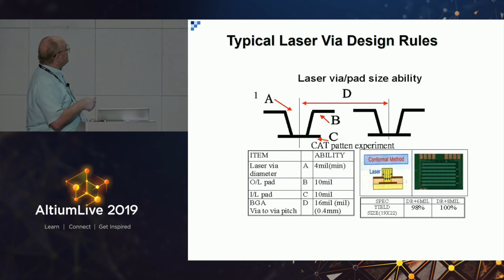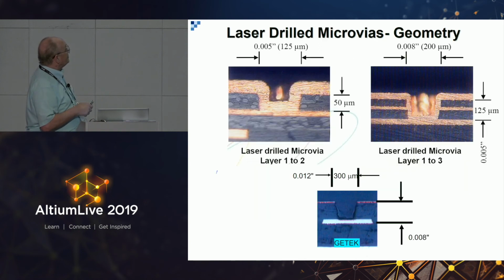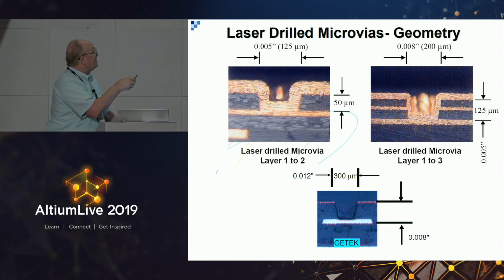And so, we don't need to talk about typical microvias. These are our typical microvias. This is what we call a skip via because it goes down 2 layers. As long as you don't violate the aspect ratio, you can sometimes go down several layers and don't have to have a buildup layer here if you can skip that. This one right here is hard to see because this is a G-Tech material, which is a 5G material. It's thermoplastic, thermoset, low loss.